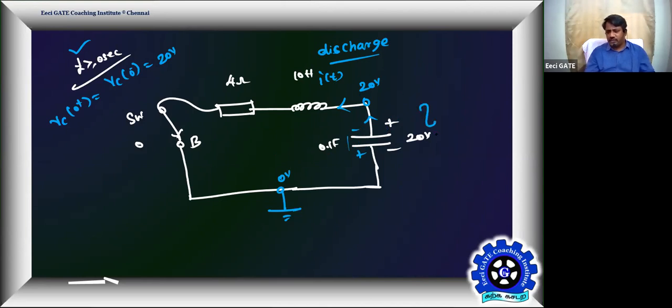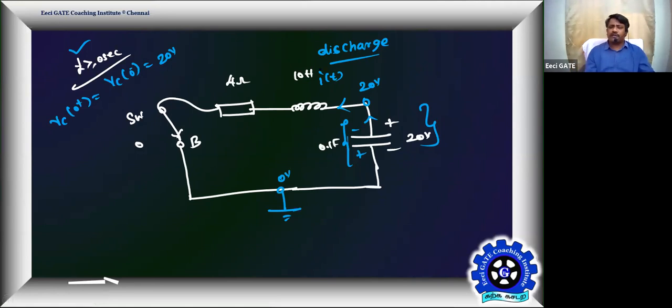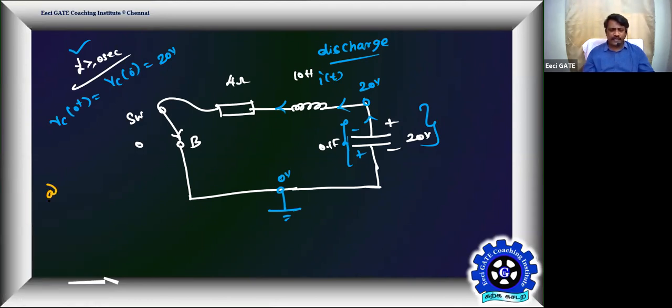This is the old charge and this is the new charge. So therefore the net charge will be less. So it is decreasing. Okay, so that's a discharge current. So the current is in this direction. That current is still 0 because earlier you know that 0 minus inductor current is in this direction, that is 0. It won't allow the change in current direction also. So the magnitude itself is going to be 0. So the current is 0 at time t equal to 0 plus.